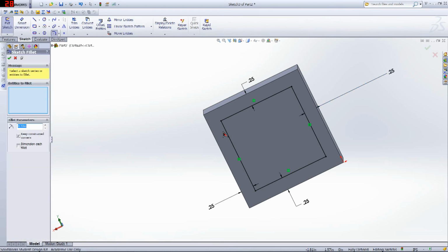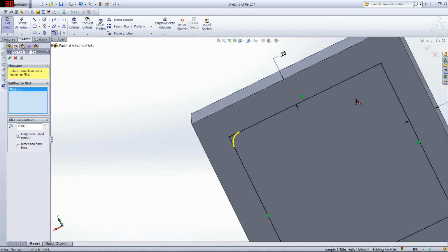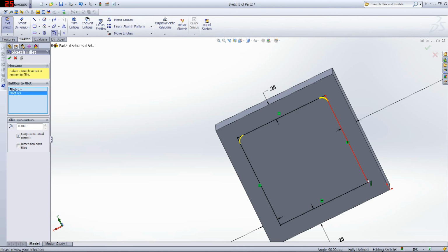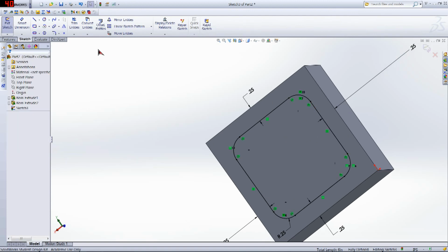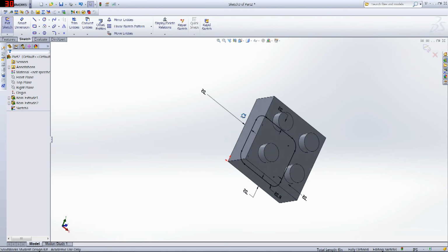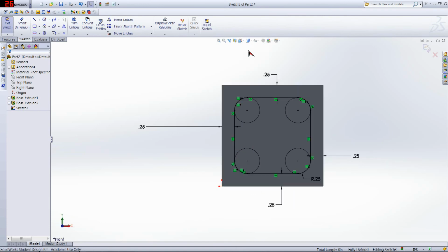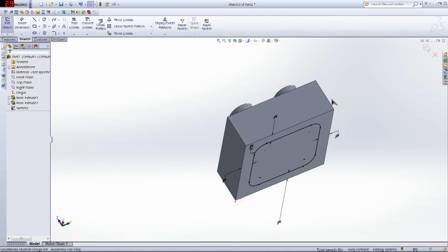So you sketch fillet, click on the first line and the second line, and that little preview arc will pop up. So do that for all the edges, and then you can change the radius of that fillet to 0.25, the same as the circles. Also, what I did right there is I hit enter twice. That'll complete the operation, and then the third time we'll finish using that tool. So now you can see that instead of just those 2 points right here, this entire edge is being used to create stability for those pegs.